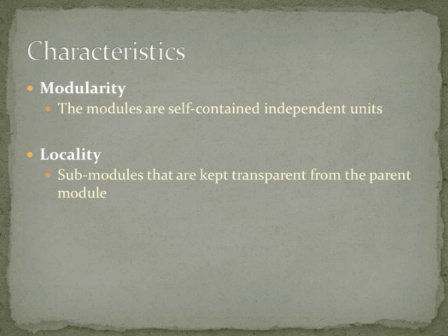sub-modules are kept transparent from the parent modules, the internal connections are hidden from the parent module to reduce details at the parent module. Connections must only be done at predefined ports, locations, and external wiring may not be able to be connected at certain keep-out areas. Regarding the keep-out areas, each layer should extend 1/2 of the design rule distance beyond the edge of the cell, and internal elements should be at least 1/2 of design rule inside the edge of the cell.